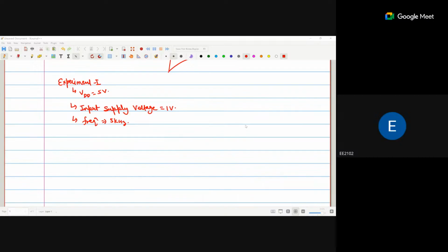Now use these values of R1, C1, R2, R3 in a way that you are getting the appropriate value. Now you can use these resistor values in LTspice, and finally check that you are getting the correct output or not in LTspice.